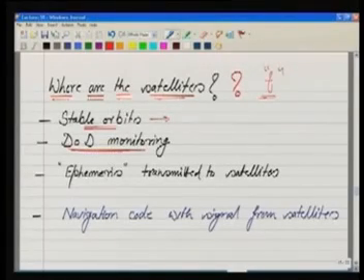So, from the ground station, the satellites are being monitored. Whenever there is any perturbation, that perturbation is being recorded by the Department of Defense, and this information is called ephemeris. So, this ephemeris is transmitted back to the satellite. The precise positions of the satellite which is being monitored is sent back to the satellite again. Why is it sent back to the satellite?